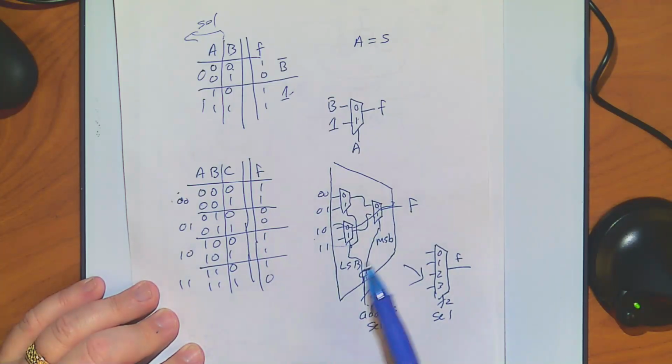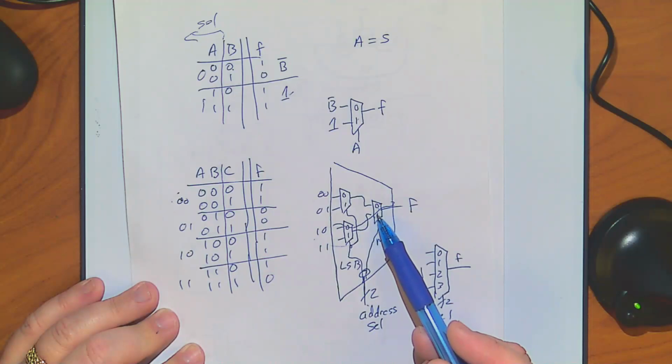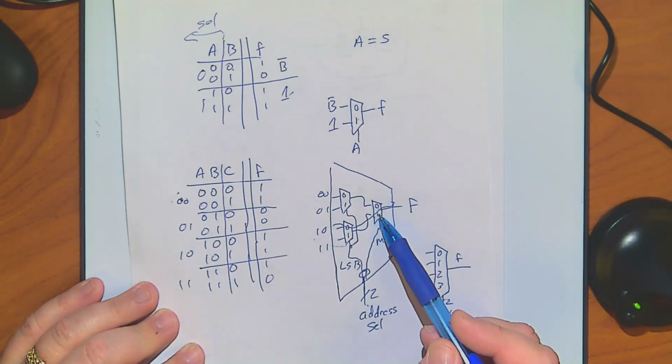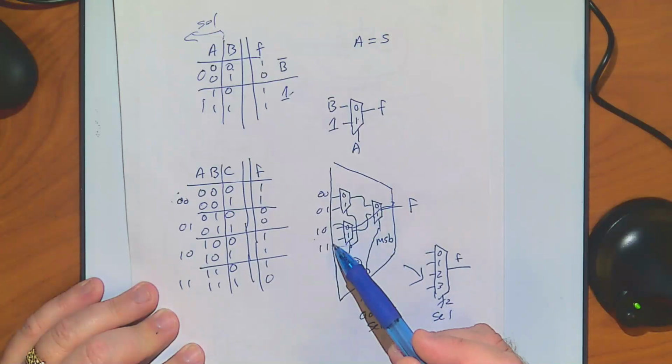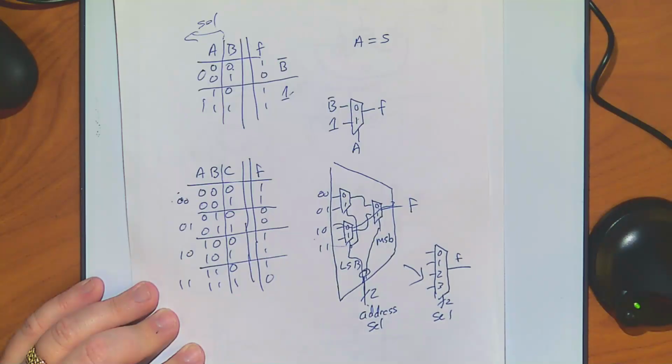So we could build the muxes as big as we want. I just want you to realize that once I've built a 2-input mux, you can make as big a mux as you want. Remember in Verilog, a 2-input mux is an if statement. So anytime you write an if statement, that's what you're getting. But I can also build any other logic gate you want. This is just a nested if, an if inside another if. This one is: if the most significant bit, then this, else this. The 0 is the else clause, the 1 is the then clause. You can think of it in that way too, and you can nest them.